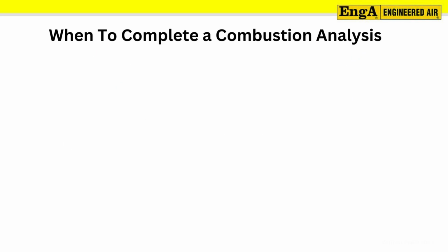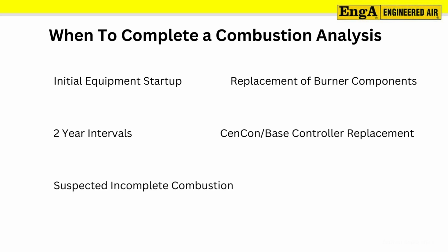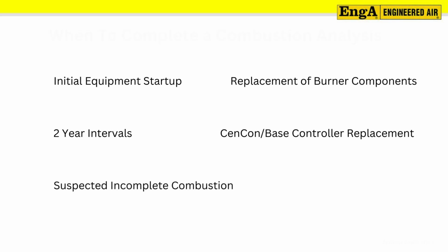A combustion analysis should be performed by a qualified service technician during the initial startup of the equipment, in biannual intervals, when the controller is replaced, when the combustion blower or modulating valve has been replaced, or when the equipment is suspected of producing odors associated with incomplete combustion.